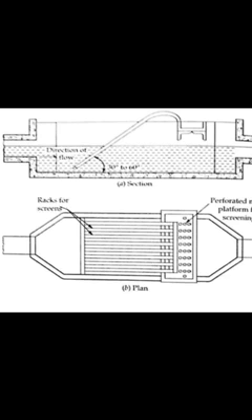So the finer screen, this type of screen has an opening a bit lesser than 2 centimeters. Earlier it was 2 to 5 centimeters, now it is a bit lesser than 2 centimeters. It is a mechanically cleaned device using perforated plates or very closely spaced bars with an interval lesser than 2 centimeters, and they need to be continuously cleaned because there are chances of clogging. So that's why it will be regularly cleaned.